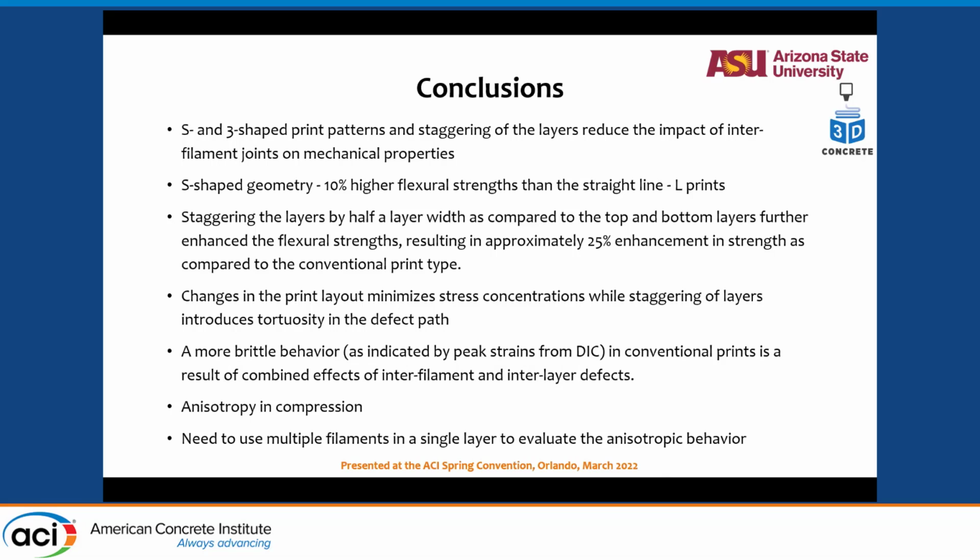Did you see any difference in crack pattern when you're loading differently, both for compressive strength and any specific crack pattern when you're loading perpendicularly for flexural strength? Yeah, so I'll talk about the compression first. There is a difference in crack pattern when you load in compression in different directions, because in one direction, direction 2, you have many more interfilament joints, which means a crack just goes through the interfilament joints. It's just a separation. You can't even say that it is a new crack that's forming. It just nucleates and goes through the interfilament joints.